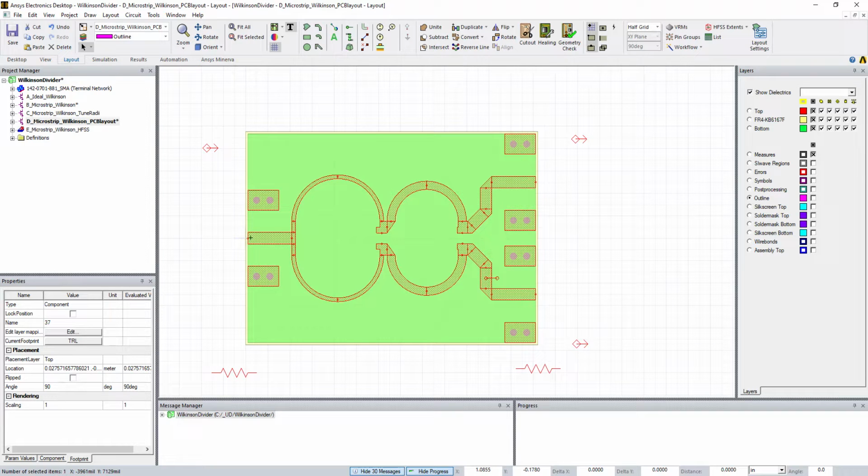So again, this launch port is by definition set at 10 mils at 0 right there. Everything else cascades along, and I can adjust the length of this by tweaking these two P launch sections. Okay, now these launch sections want to be about 200 mils long, because remember these pads right here, from here to here, that's 140 mils. So you need to have some buffer. These cannot be that close to the line. You don't want the ground pad to interact with your transmission line, so you want some buffer here. So I think my default was 200 mils, but I tweaked it a little bit. And then I adjusted these two based off of everything else to make these 0.5 inches.